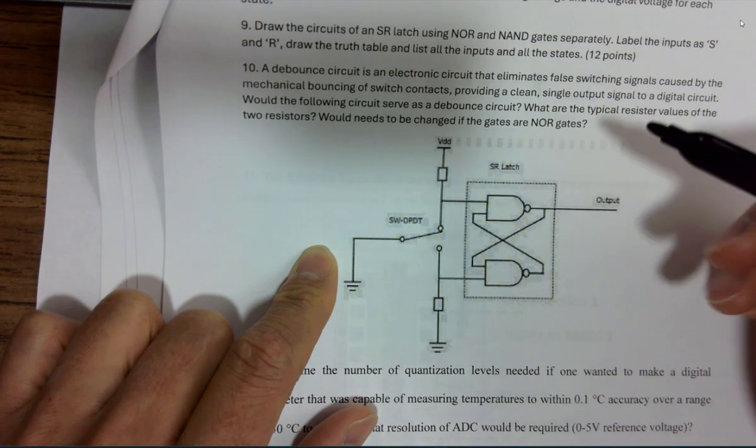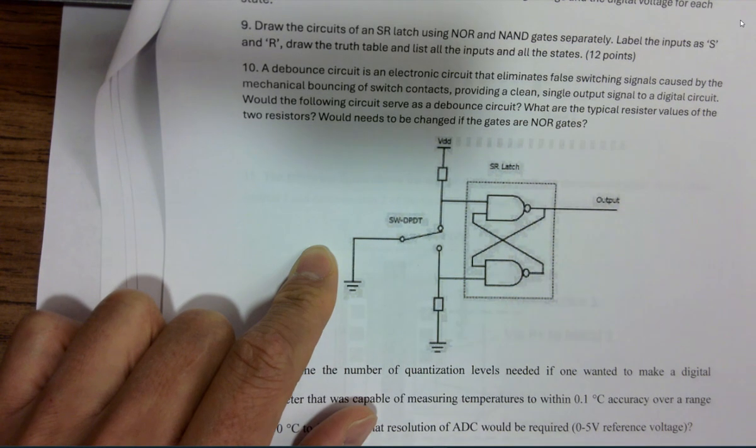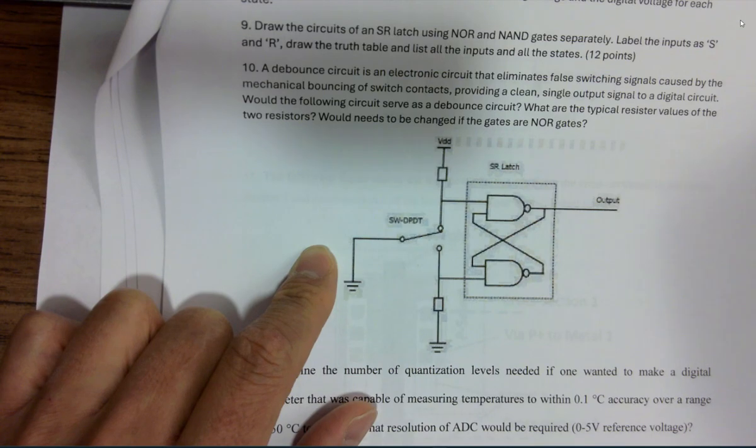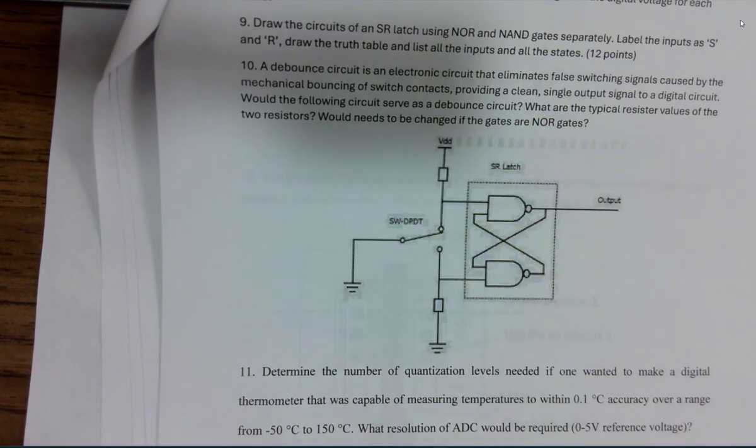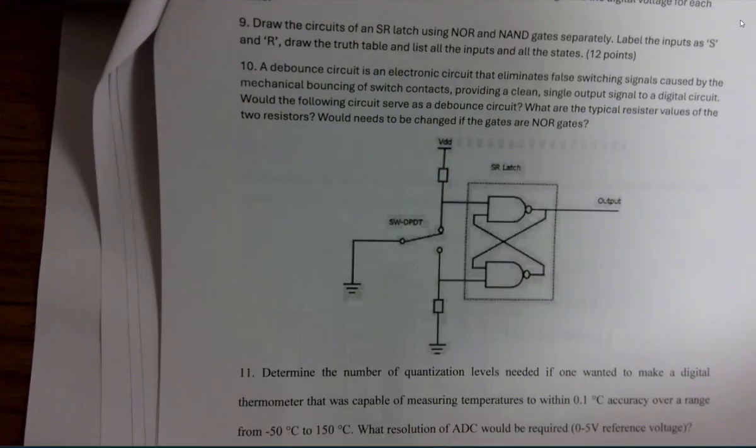Let's say 10K, right? 1K is too small. 2K, somebody uses 2K, but the reason for that is I want to use a smaller resistor, but it's definitely bigger than 1K. A smaller resistor value will give you more current, so you are able to drive the circuit at a higher speed. But if speed is not a limitation, then just use 10K. Always use 10K. Okay? It's a very safe pull-up resistor value.